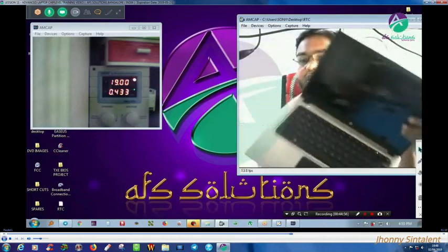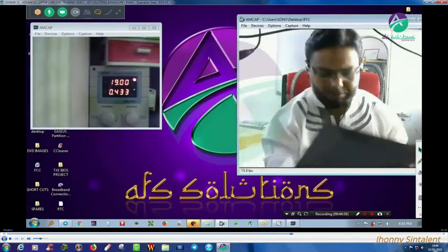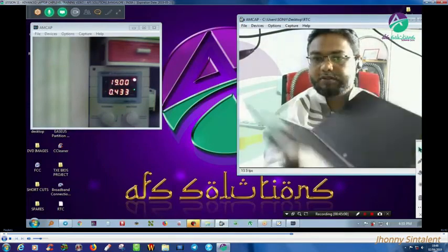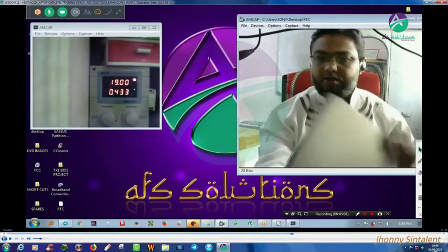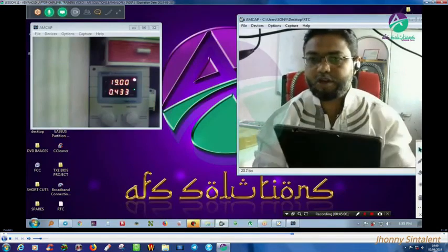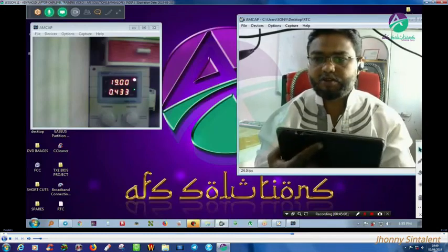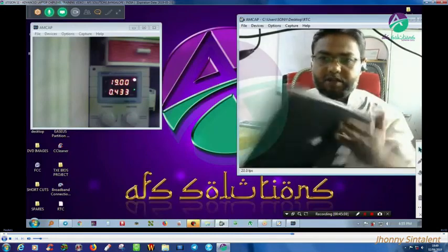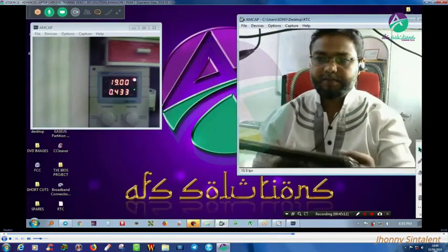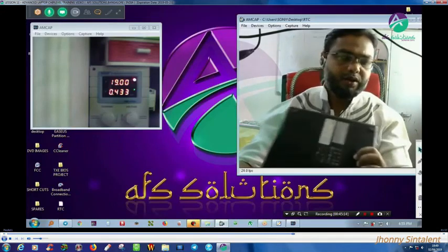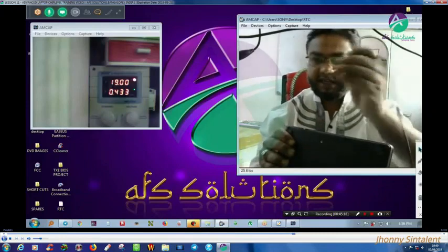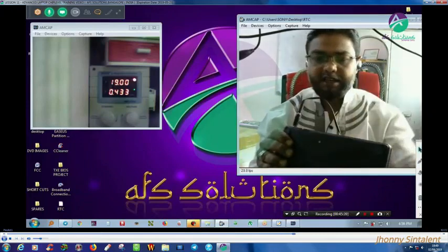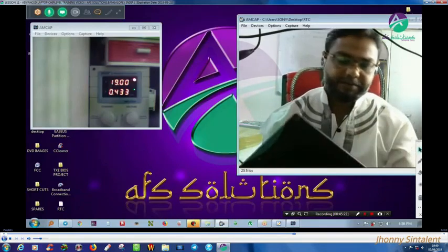You can see I have given a shutdown command. No lights. Now only 2 lights are blinking. If this light goes, the laptop is shut down completely. Now without pressing the power button, let me connect my DC jack. I am connecting the DC jack. Let me check for any lighting.